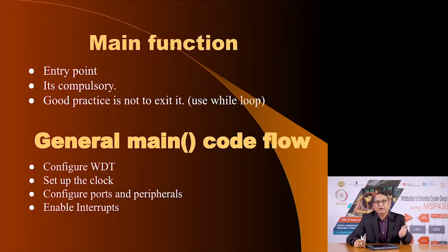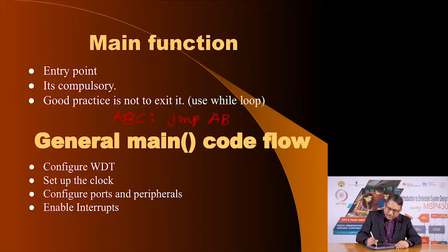As long as the microcontroller is powered, it has clock and it has memory, it will continue to execute some program. You may think that the instructions that you have written are over, the microprocessor is now sleeping, it is not doing anything, but that is not the case. It actually has an infinite loop where it is jumping to itself. So, it could be something like this. Let us say the label is ABC and it could say jump ABC. The equivalent assembly command would be jump to itself.